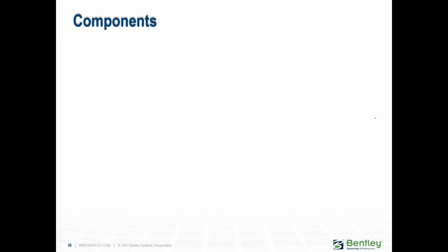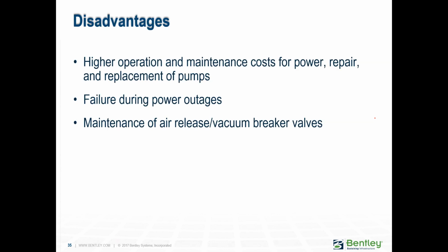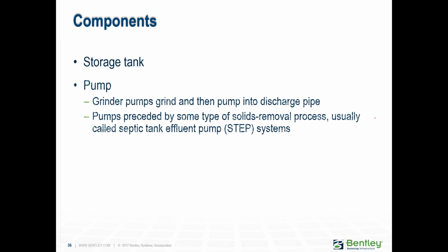You have to maintain that. And another disadvantage, actually, which is what I was talking to that student about, is that people sometimes would flush those flushable wipes that are not really flushable, and that could clog the pumps. And his pumps, actually, it was very impressive. He shared with the whole class a YouTube video where we could see the complete diapers and gloves and you name it completely gone through these grinder pumps. So now they make them really good quality, so that is no longer a disadvantage.